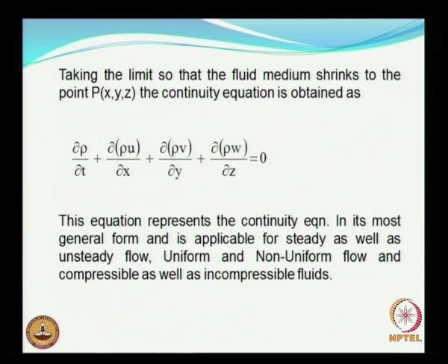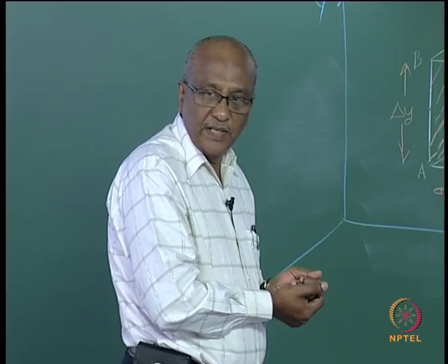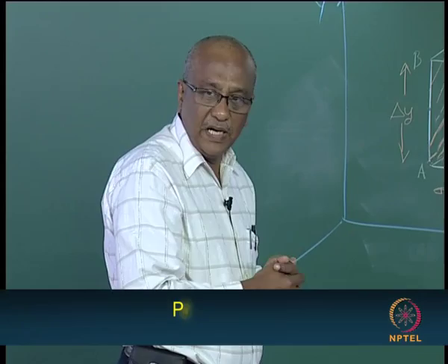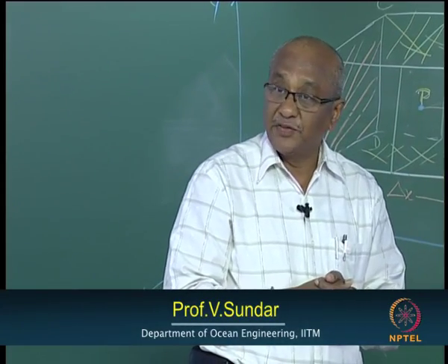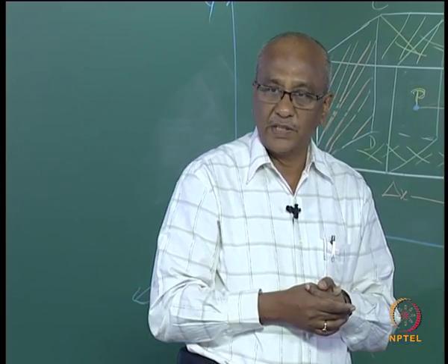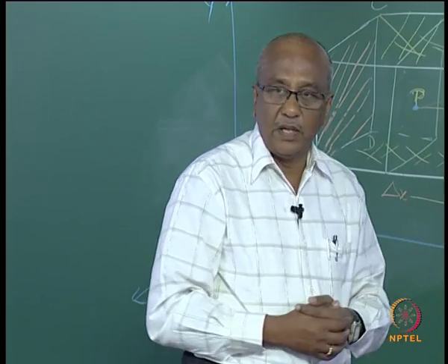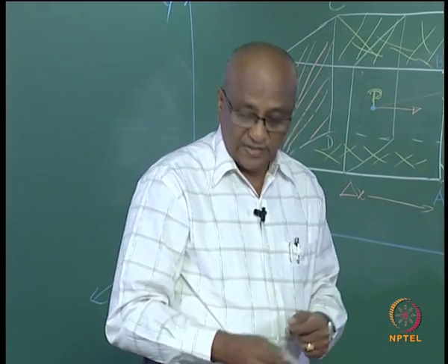This equation now represents the continuity equation in its most general form. It is applicable for steady as well as unsteady flow, uniform flow, non-uniform flow, compressible as well as incompressible. See, the variation with respect to time is considered there, variation with respect to space is considered there. So all these factors are included. So you can apply it for compressible as well as for incompressible fluids, and it is applicable for all types of flows which we had discussed so far.